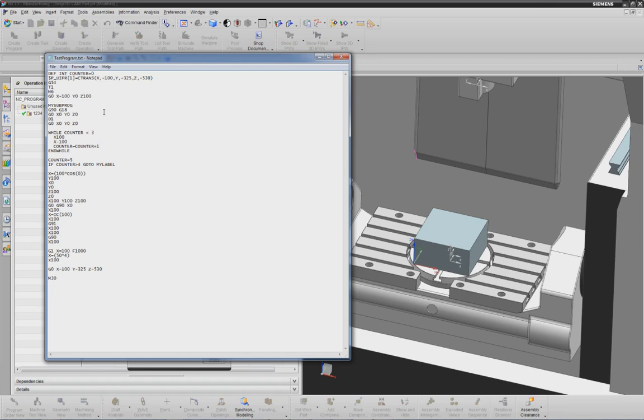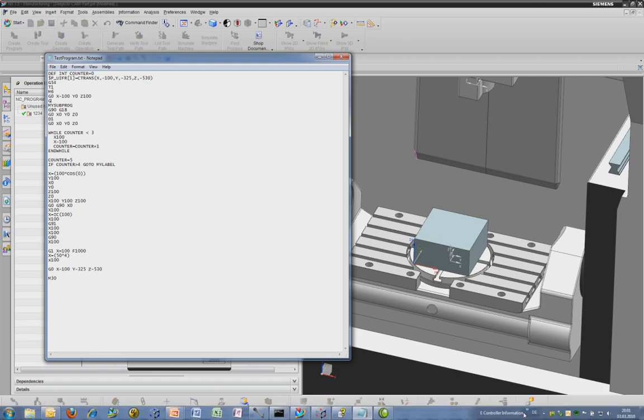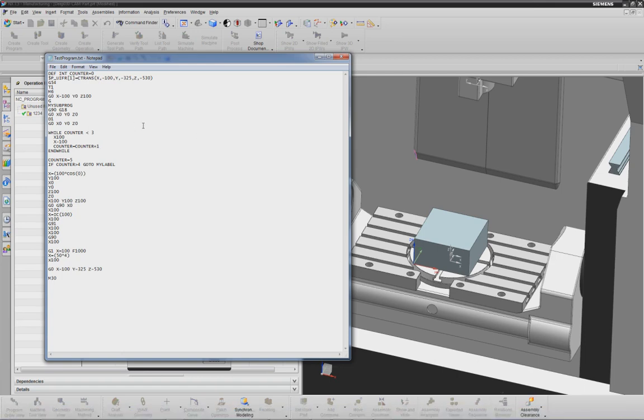The next coordinate would be to move to, so I need to activate cutter compensation, and in this case I want to go around against the clock. If my toolpath is actually the line, I need to offset to the right hand side of the workpiece, and I can never remember, but I think to the right side is G42. We could look it up in the Siemens documentation, but I think this should be correct.